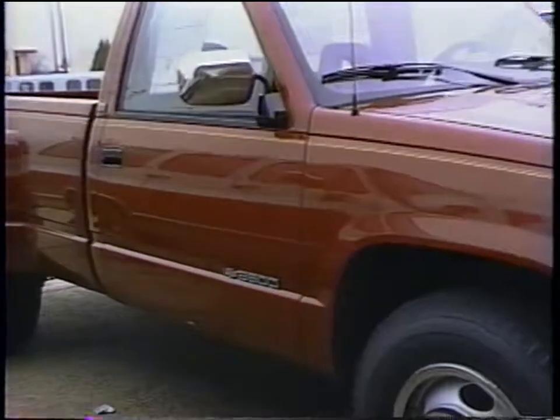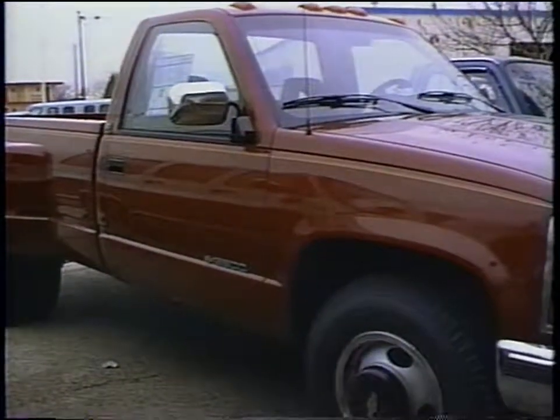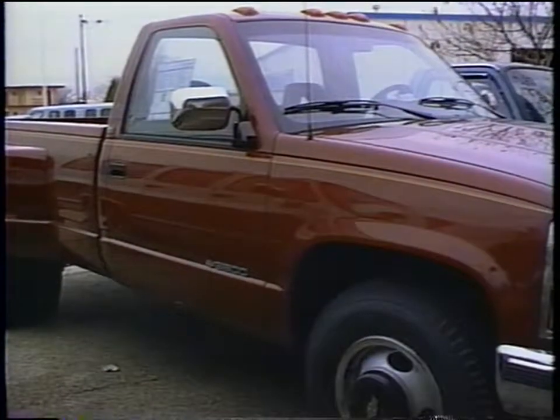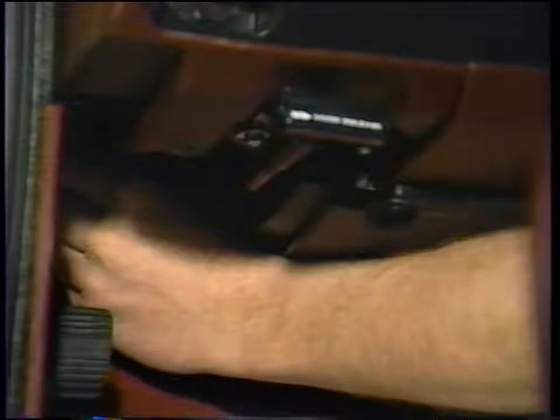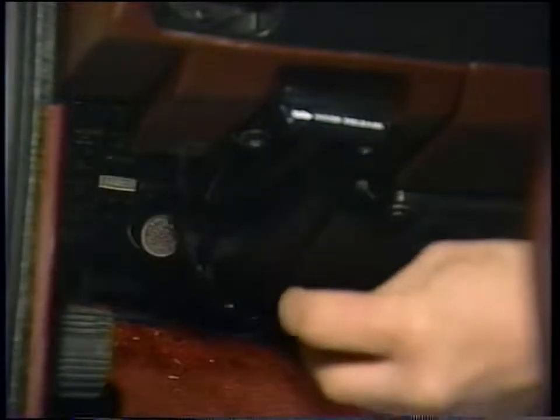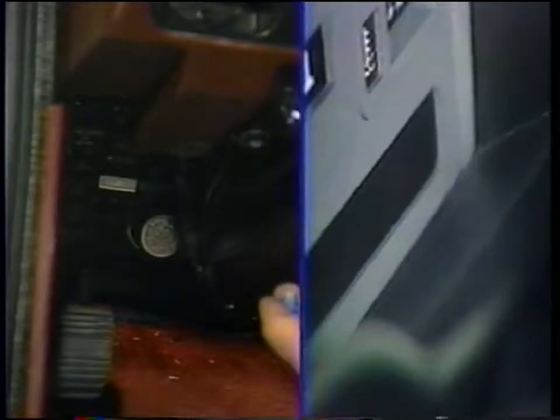To manually clear stored codes on '92 GM vehicles equipped with the ZP RWAL system, follow these steps. 1. Turn the ignition off. 2. Pull the stop hazard fuse. 3. Turn the ignition on. If there are any additional faults in the system, the brake warning light will remain on.